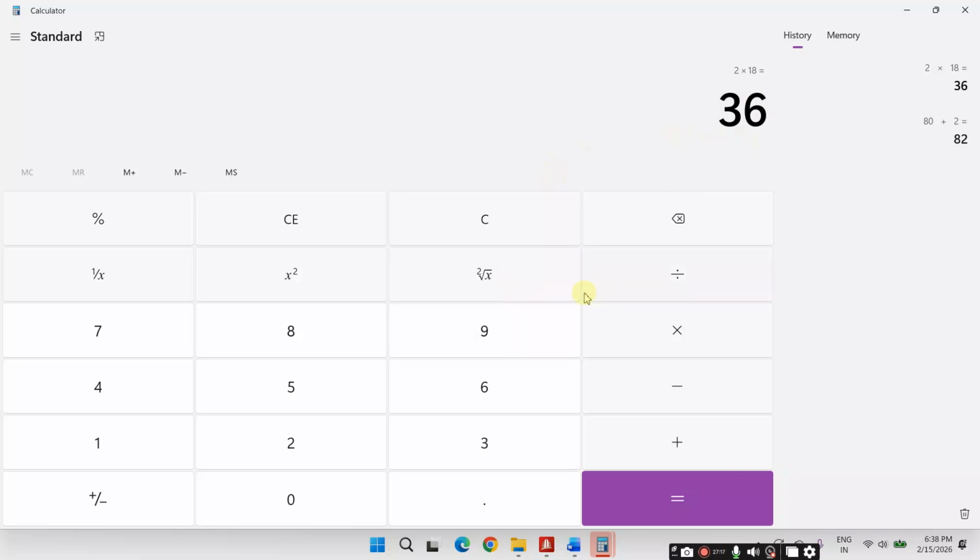So the gross pressure will be 36 plus 80 is equal to 116 kN per meter square. And your base pressure should be within this value. If the base pressure is greater than this value, then the structure settles down and the structure collapses.